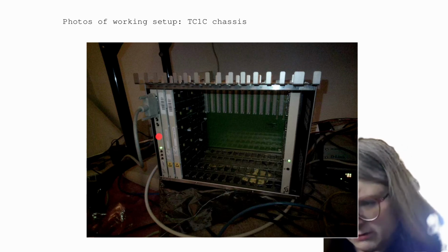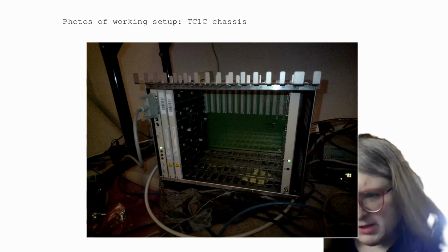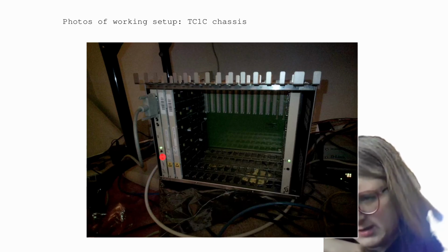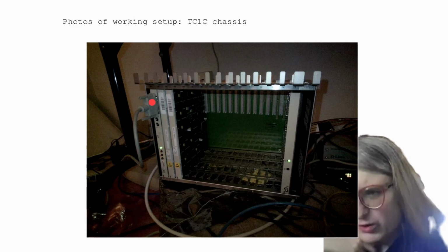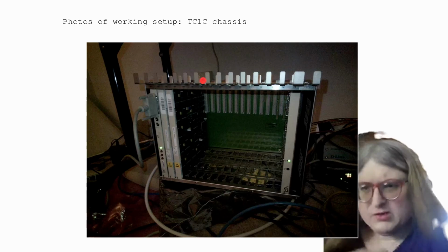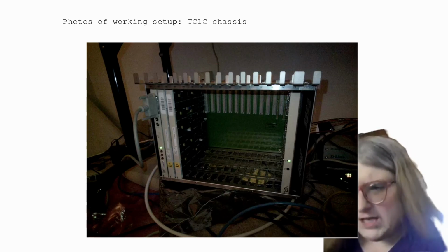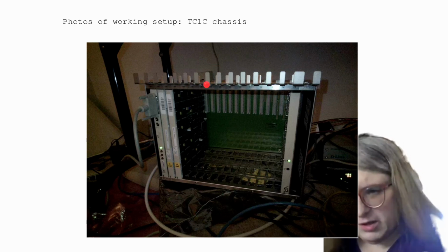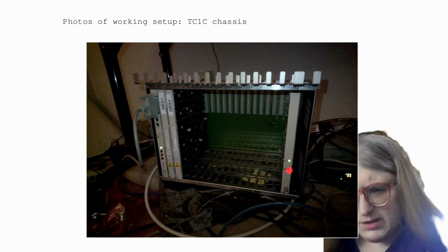The one on the far left here, that's the TRCO, the transcoder controller. You've got some LEDs here. This is a full 25-pin RS-232 serial port, which I'll get to. That's how we manage it, that's how I configure it. Then these two cards, the ones that don't have anything on the front, these are the transcoder cards. So this is the minimal configuration. The minimal functional config is the 4 cards that you see here in this picture: one TRCO, 2 transcoder cards, these are TR16s, and the power supply.